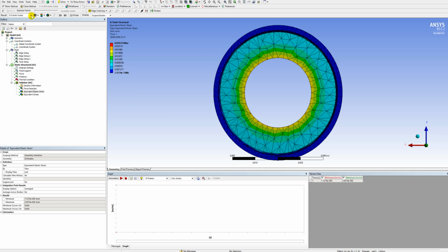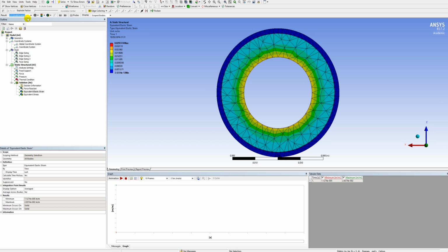Now go to the result box and select 0, undeformed. Then select 1.0, true scale. Notice how the casing changed in diameter, and that's as a result of the stress and strain. Well, really, it's a result of the pressure, force, and temperature distribution, but those go through stress and strain, so that's what happened. So the diameter changed just a little bit, and that's what the casing would look like in real life under these temperature conditions.